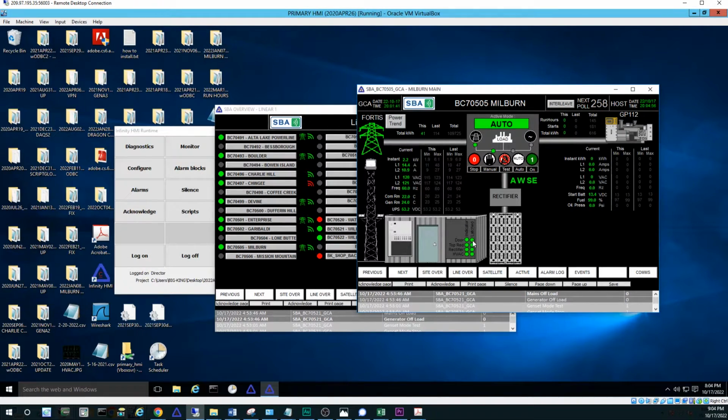If an alarm is instantaneous, the latched indicator will set, and the host will receive the data on the next poll interval. The host will reset these latched indicators after a regular poll, and it will be ready for another trigger immediately if required. All of our digital inputs are also timed and counted, and this data is logged on each regular poll. This is particularly helpful in identifying and repairing toggling sensors and failed end devices.